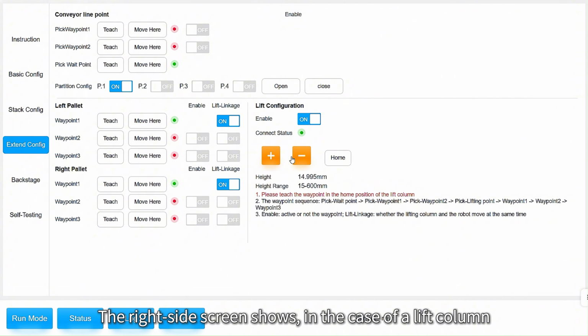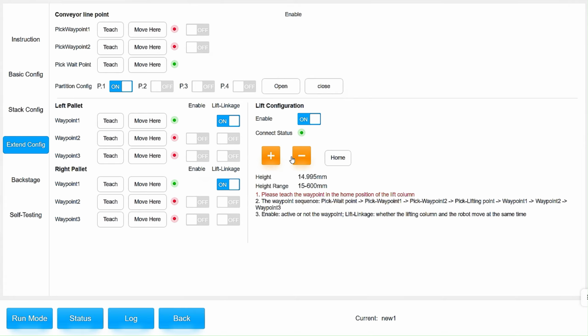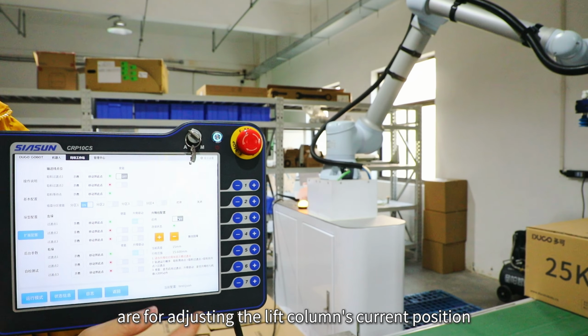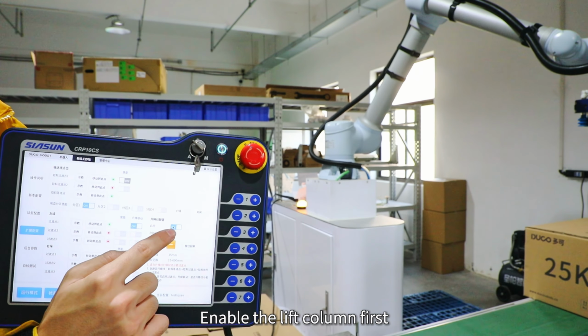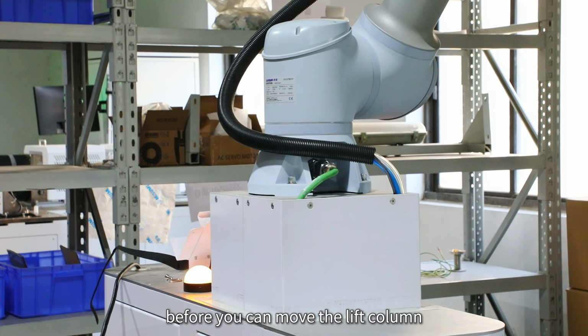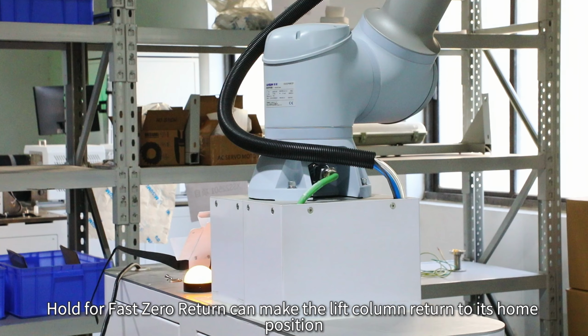The right side screen shows, in the case of a lift column, the enable and disable buttons for the lift column. The plus and minus below are for adjusting the lift column's current position. Enable the lift column first, before you can move the lift column. Hold for fast 0 return can make the lift column return to its home position.